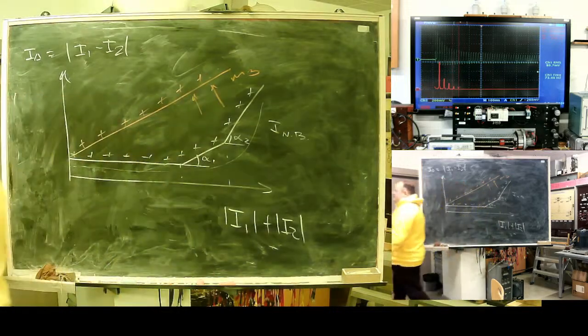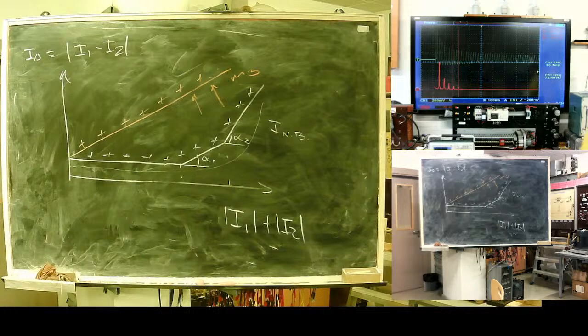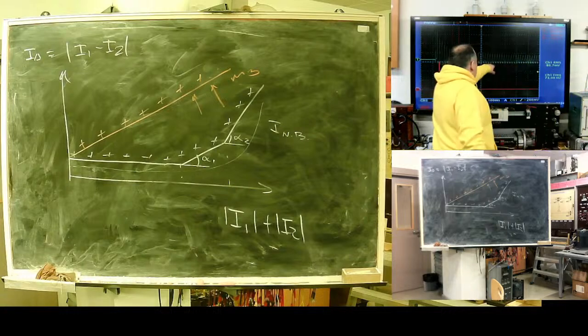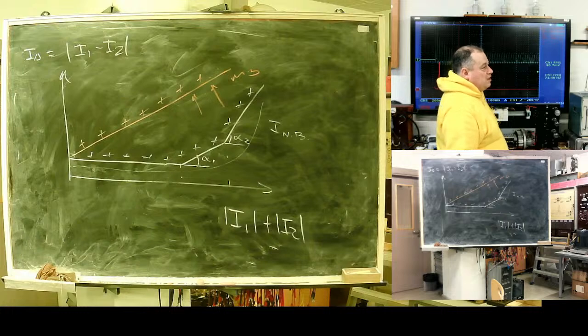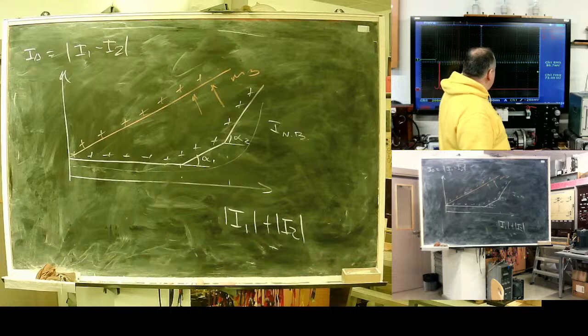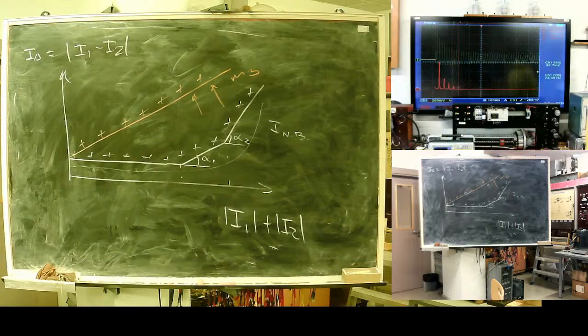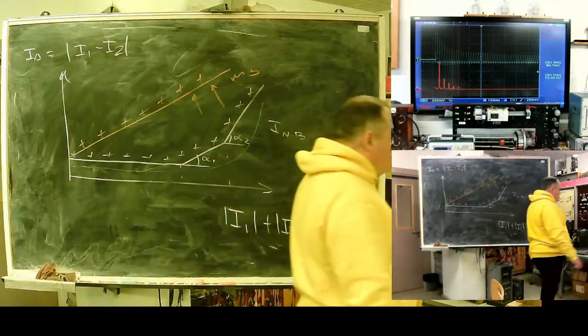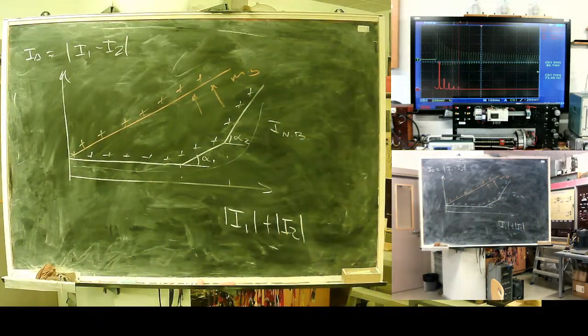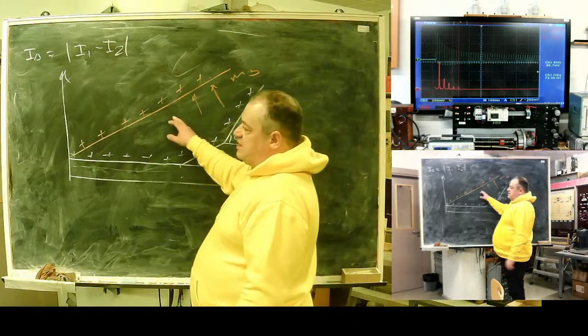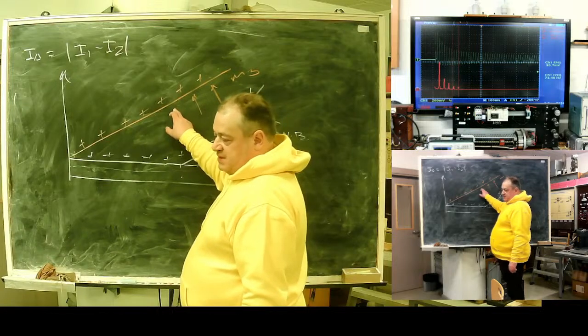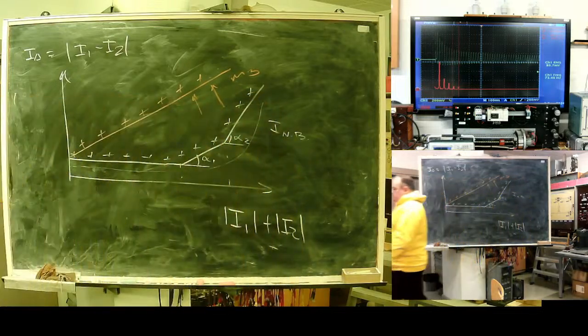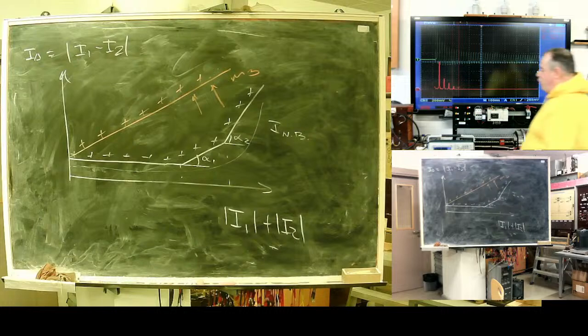It's a bad idea to disable protection if you observe this in our primary part. But we cannot remain on the main characteristic, because this current, I repeat, flows only from the primary side. So we go to a restricted, less sensitive characteristic. It should be selected to prevent false operation.